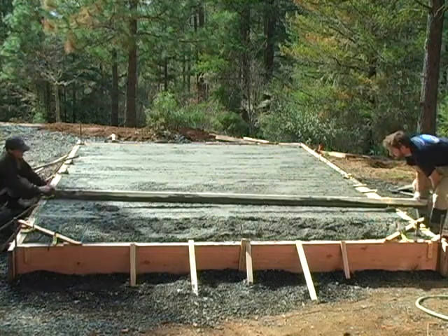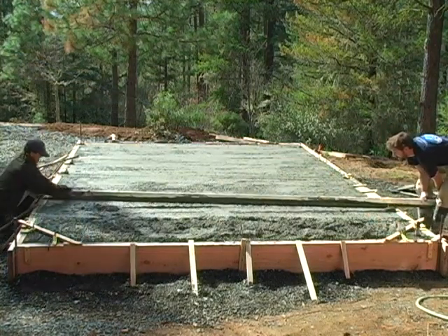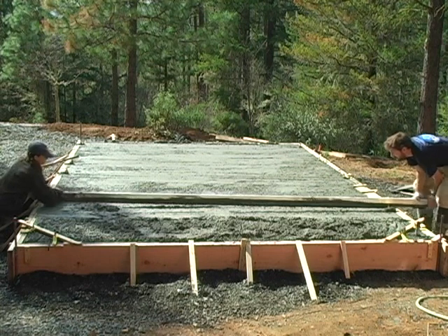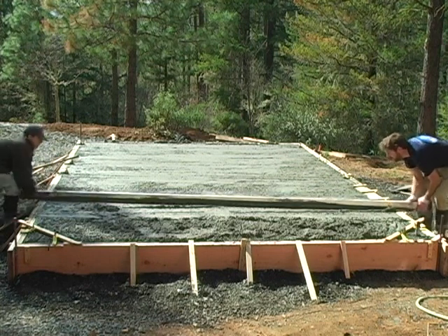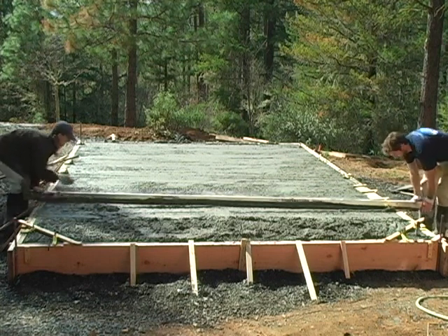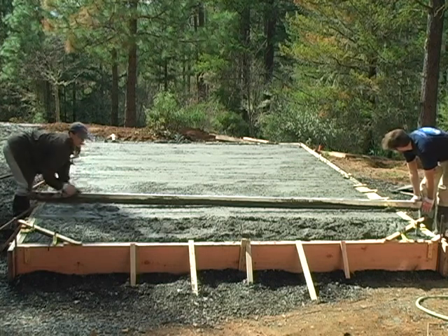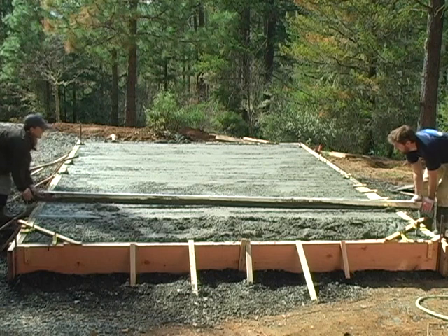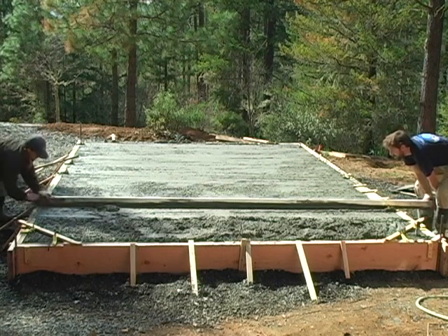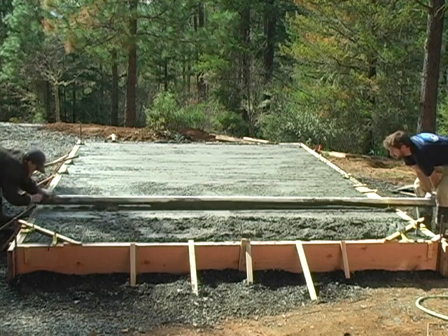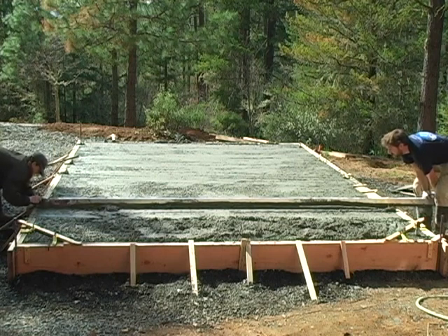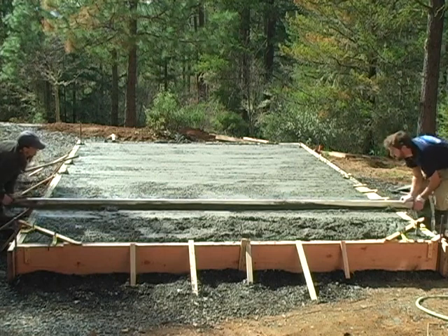Once you've got the form boards pretty much filled with concrete, you want to run a screed board across the top. And you can see we've left a little bit of room down at the end here where we're sliding towards, so that any excess concrete will fill that void. If you put too much concrete in at once and then try to screed it out, it just becomes really tiring, and it's hard to move the concrete along, especially with a dry mix like we've used on this project.